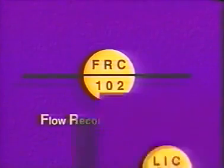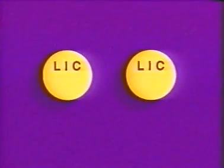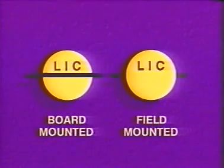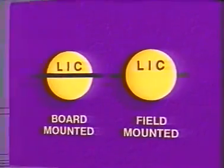A circle like the one on the left with a line drawn through the center is a panel or board-mounted instrument. A circle like the one on the right indicates a field-mounted instrument.